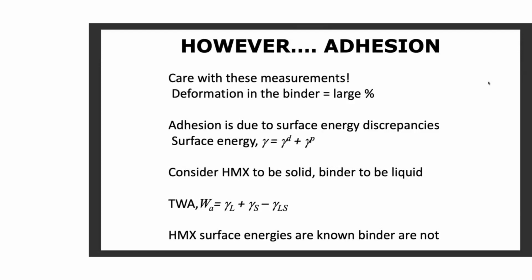So in that case, we became very interested in what we call the thermodynamic work of adhesion. We know the surface energies of the HMX crystal. You can look them up. However, those of the binder were not known.